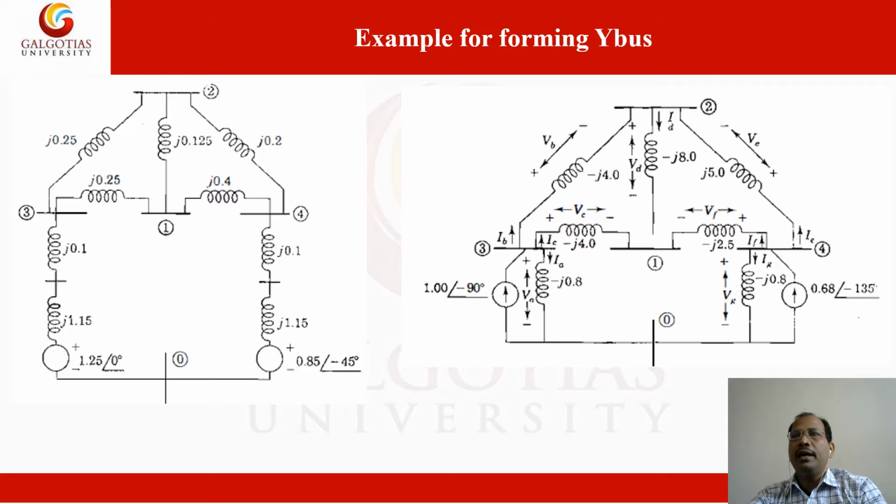Here we are considering another example. So suppose this is the system they have given. Here also there is a 4 bus system. This one is bus 1, this is bus 2, bus 3, and 4. In between, all the transmission lines are represented only by admittances. The reactance will be 0; we are considering that for simplicity. And here bus 3 and 4 have the generator, with all the generator values given. And this is the reference bus. So all the induced voltages and angles they have given.